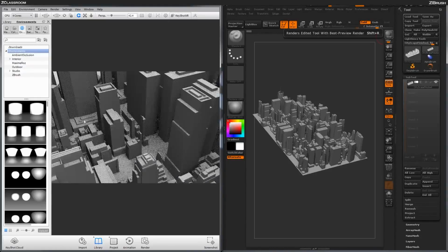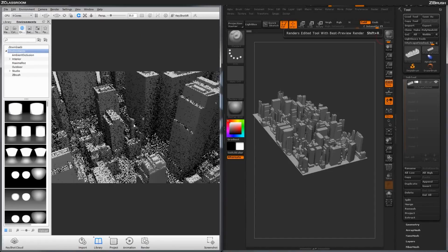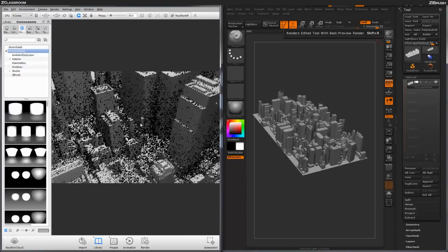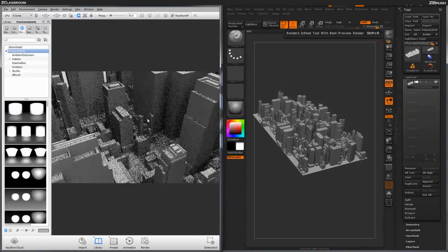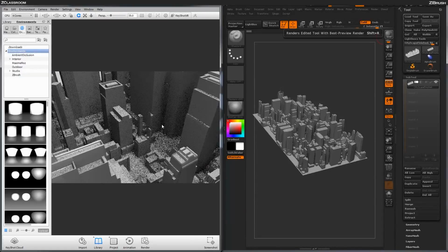Now we can change our perspective for the camera as well. So we just come up here and type in the perspective value we're looking for. So I'm going to go for 35 and just click that, and that's going to update. And then we can position our scene and move stuff around until we find an angle that we actually like inside of KeyShot here.